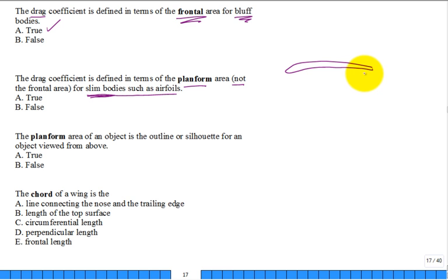Remember, the drag force can be made up of two components. The pressure and the friction. Which one would typically dominate? It's going to be the friction component dominate. I don't have a large wake. I don't have a lot of separation. And so I don't have a high pressure on the front and low pressure on the back.